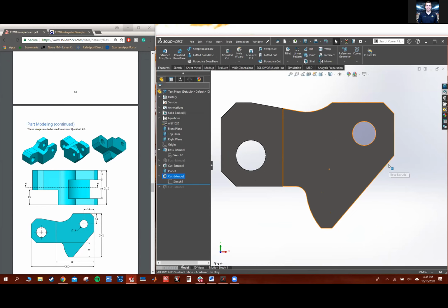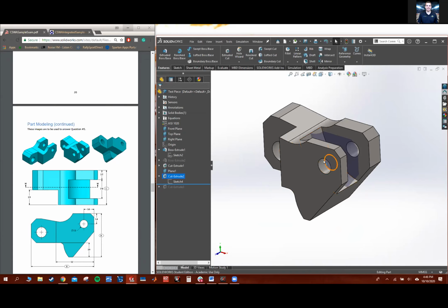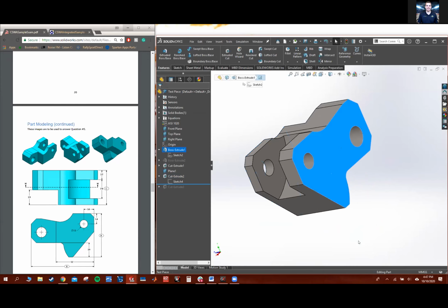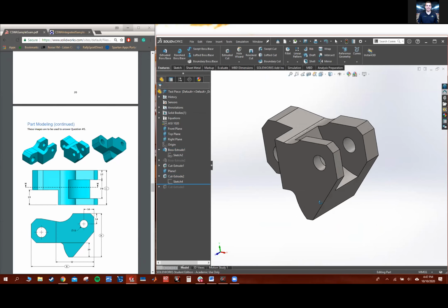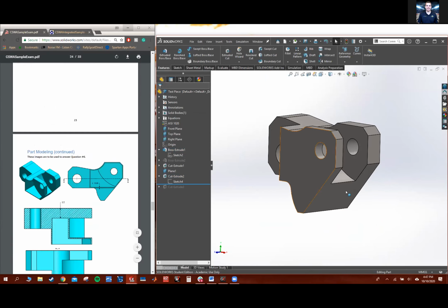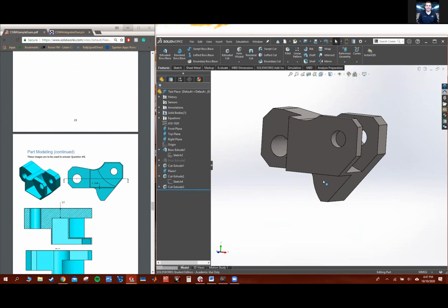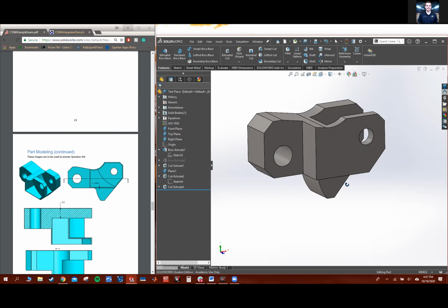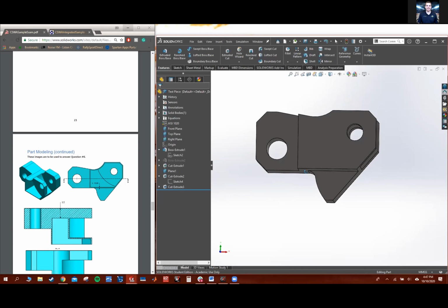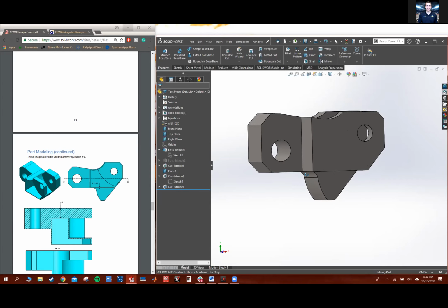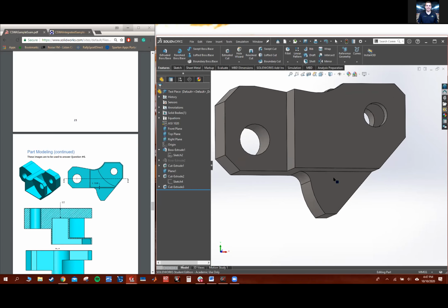And then that was pretty much it. I had already added the hole in my initial sketch, but if the hole wasn't there, you could sketch on this front plane and just do a through hole all the way to this surface. But essentially, once your part's created, oh yeah, I also cut away this piece. Same concept as before. You're basically just selecting the plane and then cutting, or selecting your offset, or your converted entities, and then cutting away at it.